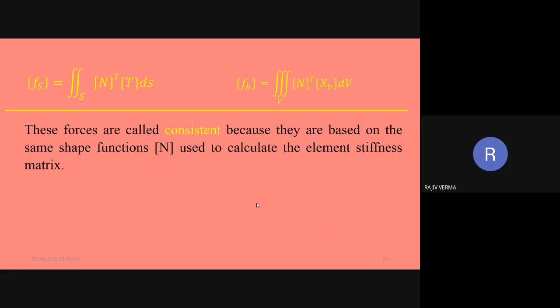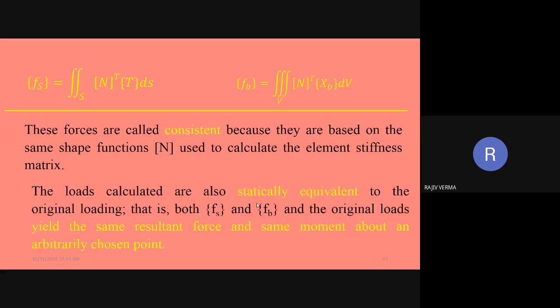And the other thing to be noticed is that the loads calculated are also statically equivalent to the original loading. This means that both Fs and Fb and the original loads yield the same resultant forces and the same moment about any arbitrarily chosen point. So they happen to be statically equivalent also.